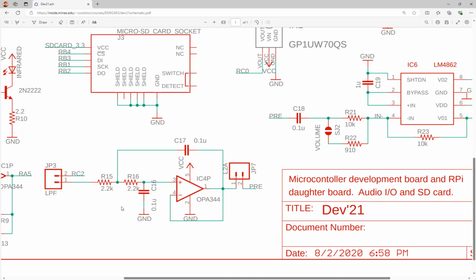If you don't filter out noise, you are still getting pulses from your microcontroller, just a square wave, like the timer controls the frequency of the note, right? It's okay. It's just a 3.3 volt square wave. You can still directly connect that output to the audio amplifier. It's going to amplify it, buffering the signal and giving more power to it.